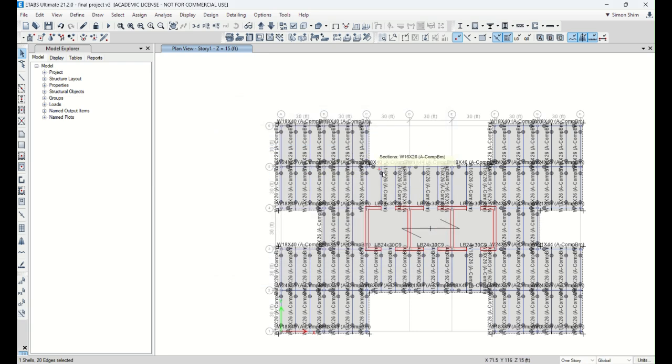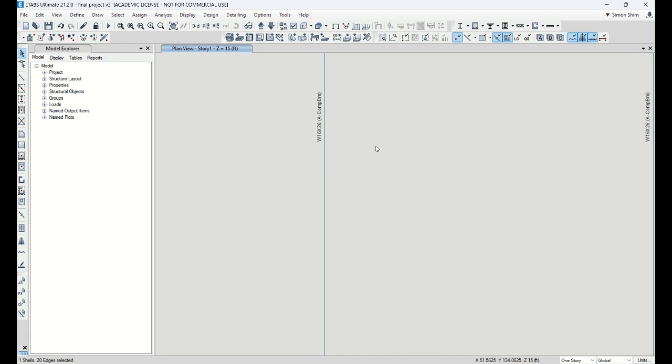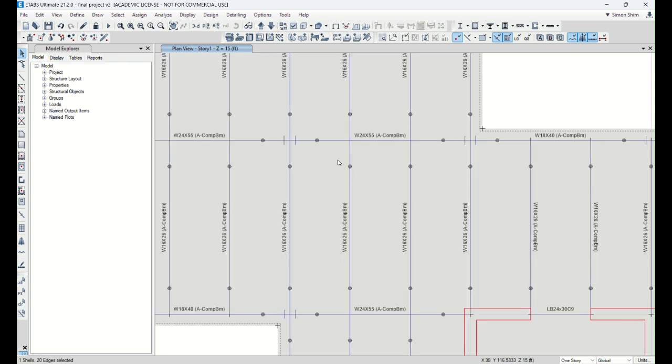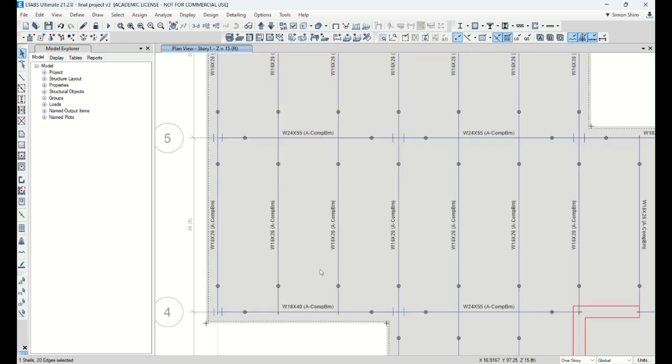So, okay, up to this floor, I'm just using my brain. I think you probably already designed this typical floor so that you end up with W16, right? So W16 for a 30 feet span seems reasonable because we have a live load of 100, which is quite significant. For the girder, you could see what kind of girder size? 24, right? 24, 18. It depends on your bending moment demand. Nothing new. This is common sense. We already know it.